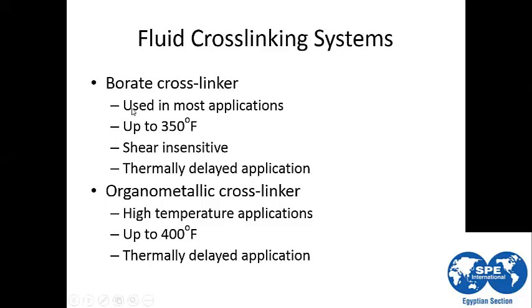However, the Borate crosslinking system is shear insensitive, which means that if the fracture fluid is subjected to shear force, like when it is passing through a restriction in the frac string or through the perforation itself, the shear force applied on the frac fluid increases. Once this shear force is applied, it reduces the viscosity.